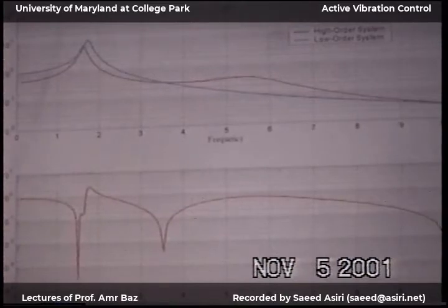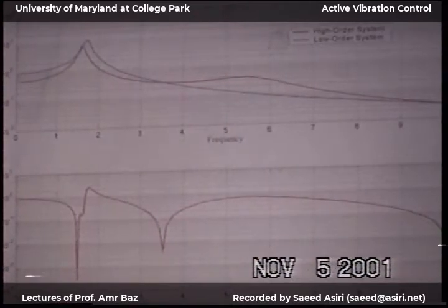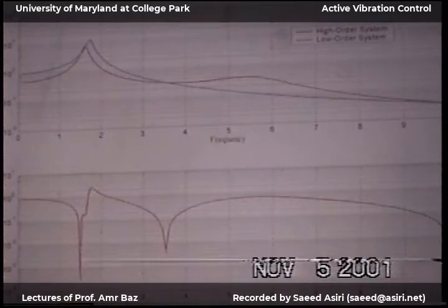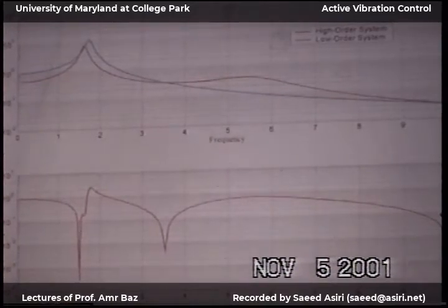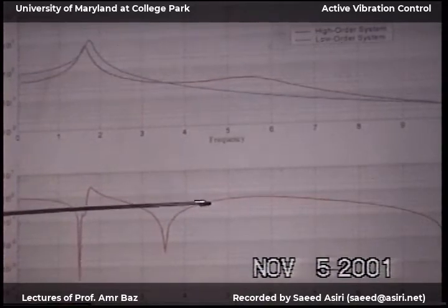Now this maximum bound on the uncertainty level has to be lower than this to be a stable system. If I know this exactly, then that's fantastic, but it defeats the purpose. I will say I know the system within 5, 10, 15, 20% error. And the higher you make this, the lower the performance has to be, because you cannot have very high doubts and get excellent performance. If you know the system exactly, then you'll get the best performance. The more you put doubt on your knowledge about the system dynamics, the more the performance will degrade. So now this is my uncertainty.